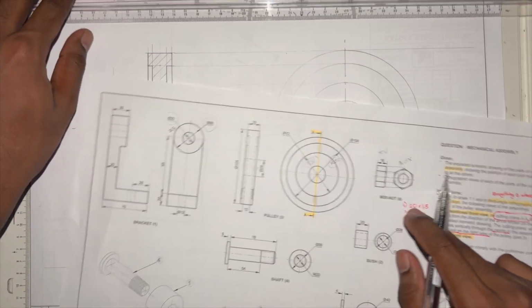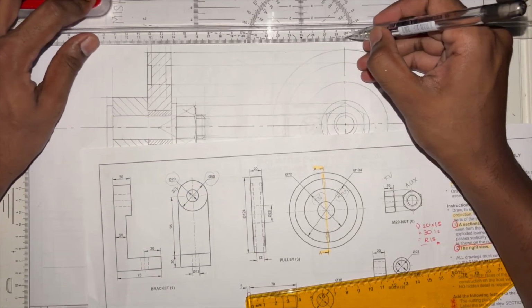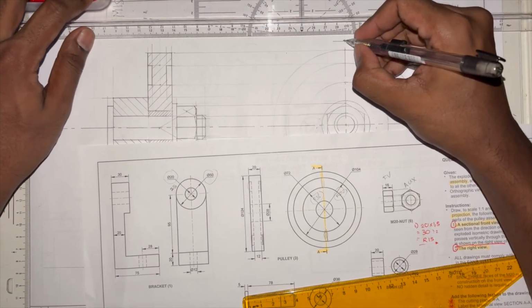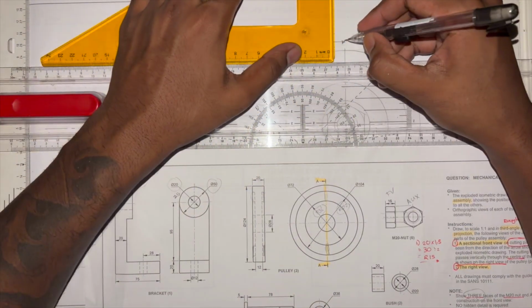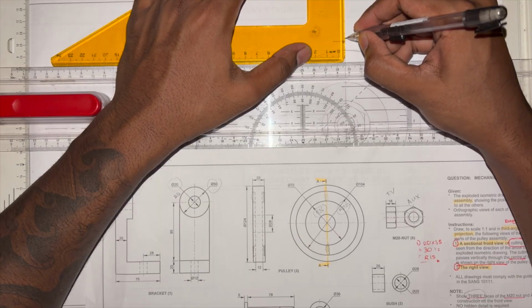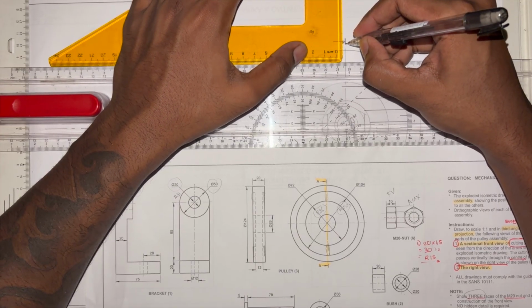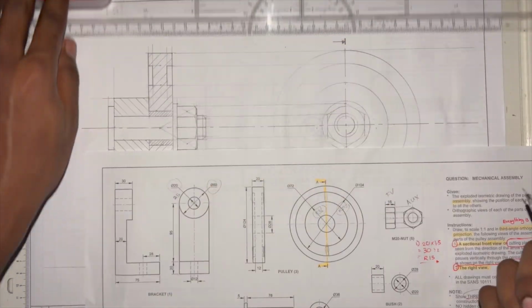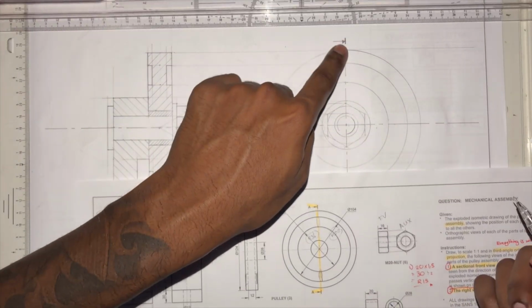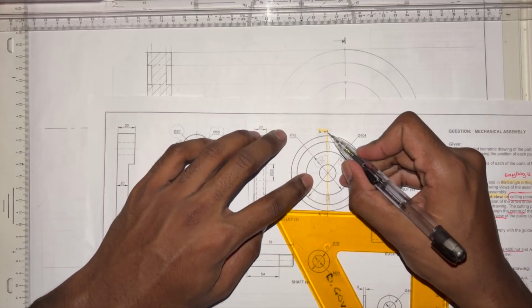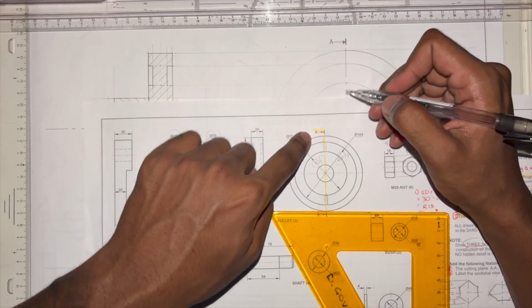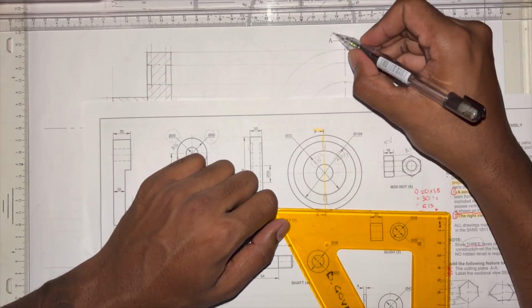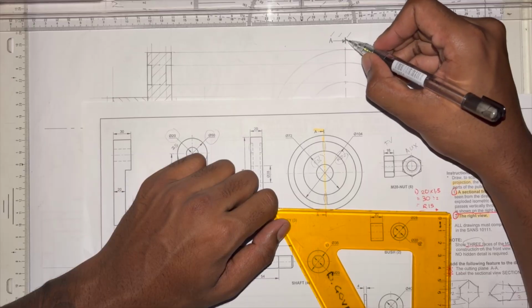And I'm also going to show you the line weighting. Okay, so I can use this, draw an arrow here. Next, you need to give this a little bit of thickness to make it a cutting plane. So the center line is drawn, just give that a little bit of thickness, just like it is here. Replicate this is what I'm saying. And then draw the letter, the alphabet A. You'll get a mark for the letter, for the arrow, and for the thickening of that line. Do the same thing at the bottom.